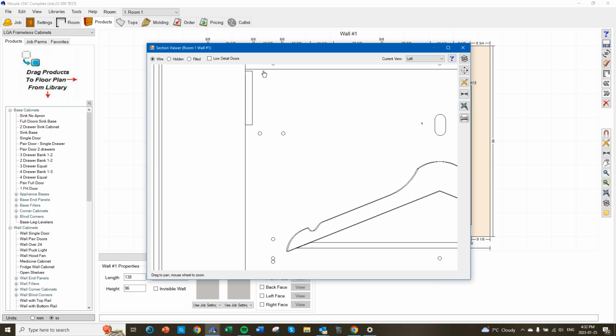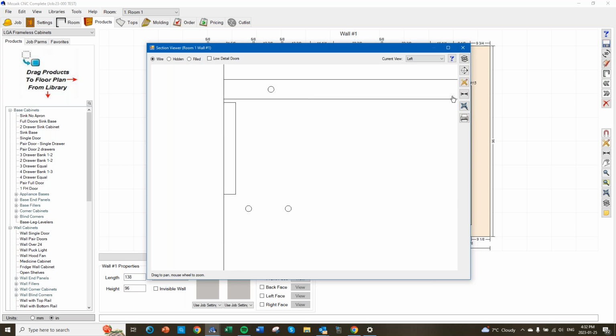What about top to bottom? Are they okay there? Or do you want to raise them up or down? Yeah, they are okay. It should be 108 from the top to the center. So 4.25 times 25.4 is 108. Yep, that's correct. So then we just need to take this guy, and how far down do you want to have that from the top here? Because right now, it's only 3/4, and that's got to go down to 2.5, right? Okay.